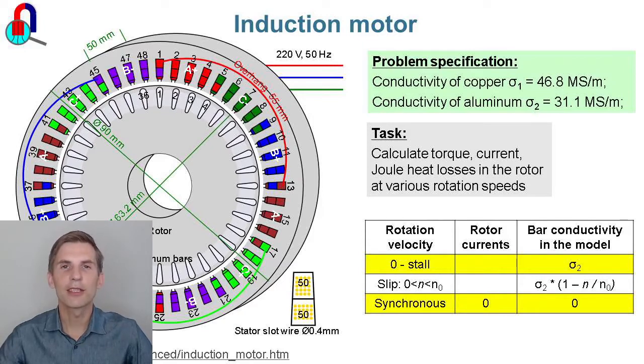Now let's consider our options. When the rotor is motionless, the speed is zero. The stator magnetic field generates currents and there is a torque. We can model this very simply. Draw motionless stator, motionless rotor, specify currents and calculate the torque.